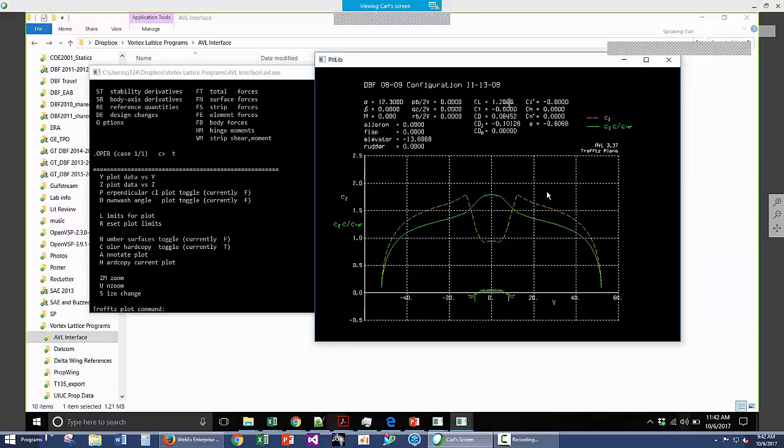All right, so we got a reduction in our lift, and we have an increase in our elevator deflection required. So here it's taking negative 13.7 degrees, which is trailing edge up. So our elevator is trailing edge up when elevator deflection is negative. But our CM here is now 0. And so this is the trimmed CL max, approximately. And again, I can vary this a little bit, but you see that we actually had a reduction in our lift. Right, so the CL max is nice. We can go through and trim it.